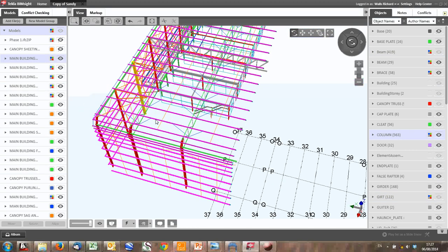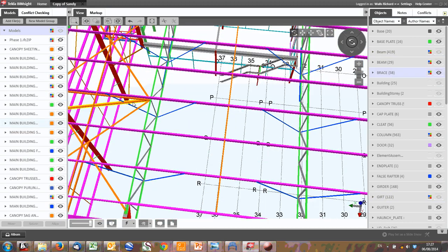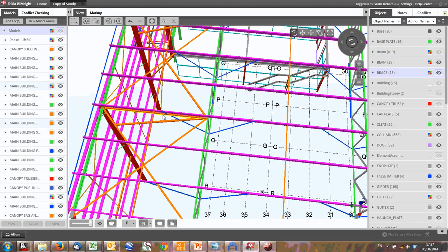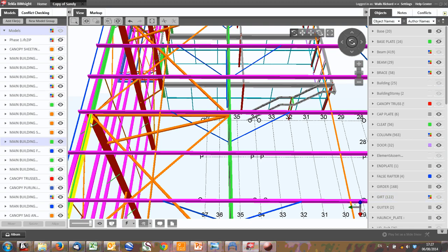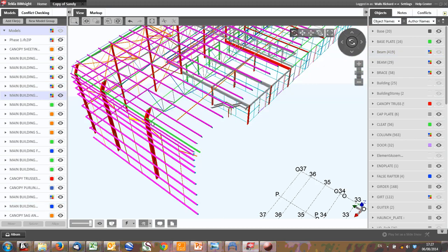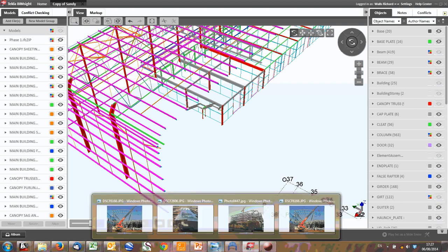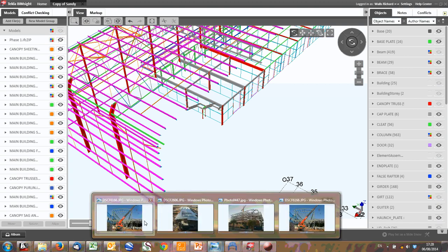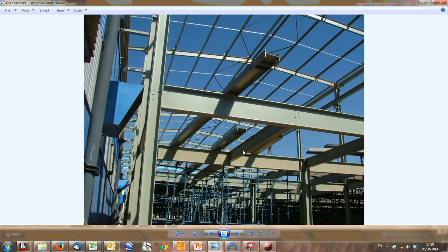For instance, let's say you couldn't put braces here for some reason. If there were penetrations to the roof or ducts or something weird, and you couldn't put a brace bay here, you put it in the next bay, then you just take your pipes all the way through. So you go through that bay. So there's your pipe in orange there, I've highlighted. You just put one there and one there. You can take your load down there and then take it out the door. So that's ways you can actually move forces through until you can get them to a place where you can handle it. So now I hope that has given you a very good introduction to structures, because you need to get an understanding. When you look at a structure, say, if wind is applied from there, if dead load comes there, if live load, if all these sorts of loads, how do I carry it through the structure?